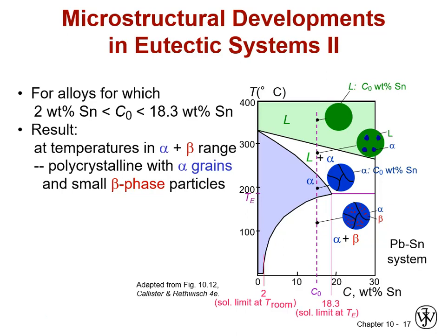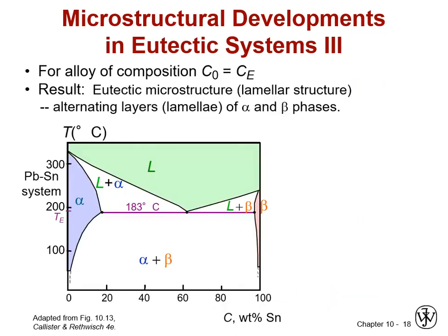And from the time that we hit the alpha solidus, we were dealing all with solid phase movement. So to make these phase changes and to move the tin and the lead around in the microstructure, we are relying on diffusion. So we know darn well that this will probably mostly be precipitating at the grain boundaries. But nonetheless, we do have two phases there. And so that's what the red dots are showing, that we have beta phase. I'm just making a debate about exactly where it's likely to be present in the greatest abundance.